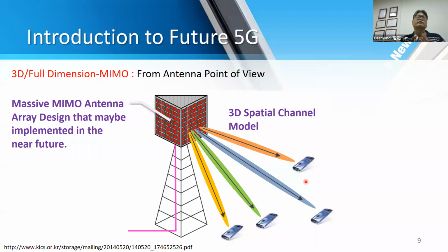The next issue is heat, because the power input into this kind of base station will be about 6 to 7 times larger than our 4G cell, meaning you need a large heat sink to dissipate all the heat. But at the moment, because you are given such a small volume, we can't dissipate the heat.